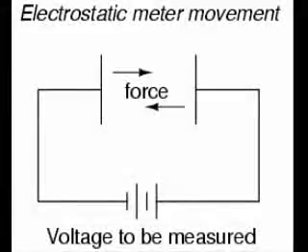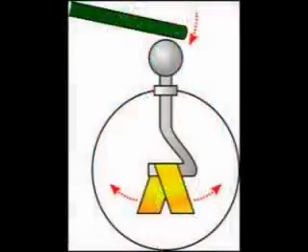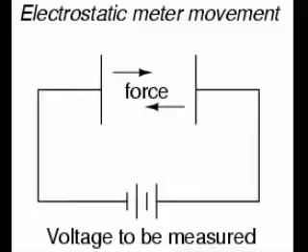While most mechanical meter movements are based on electromagnetism, electron flow through a conductor creating a perpendicular magnetic field, a few are based on electrostatics, that is, the attractive or repulsive force generated by electric charges across space. This is the same phenomenon exhibited by certain materials, such as a charged balloon with popcorn stuck to it, when rubbed together. If a voltage is applied between two conductive surfaces across an air gap, there will be a physical force attracting or repelling the two surfaces, capable of moving some kind of indicating mechanism.